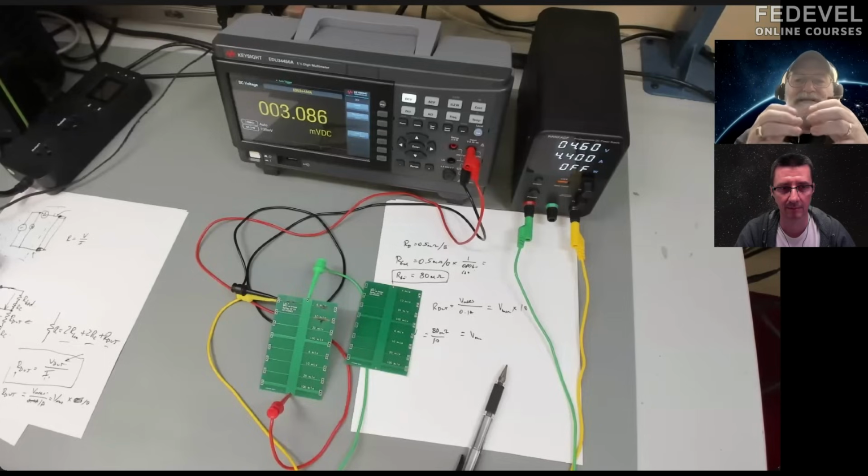And then as that via makes contact to the power plane and the ground plane, you have to worry about the spreading resistance in the plane. When you get to that point, there's a limit to what you can do with simple approximations and rules of thumb. That's where a 3D field solver helps you understand what the current paths are. Those 3D current paths and spreading currents go from the plane into the vias and the distribution of vias, and then up into the package and through the package.